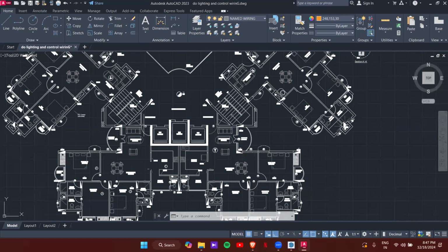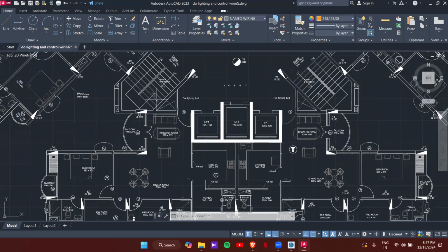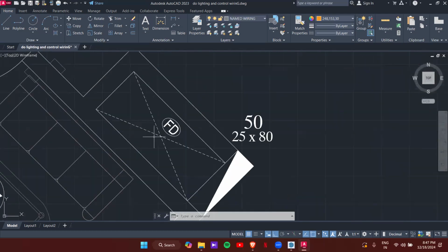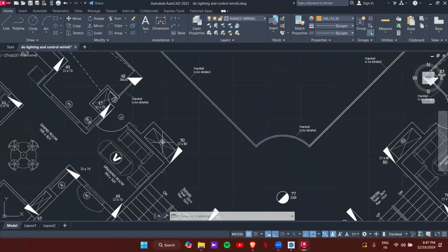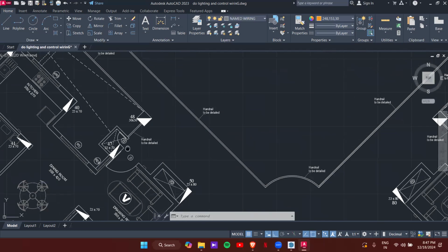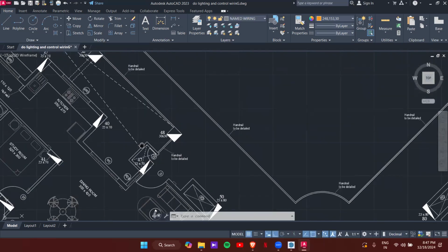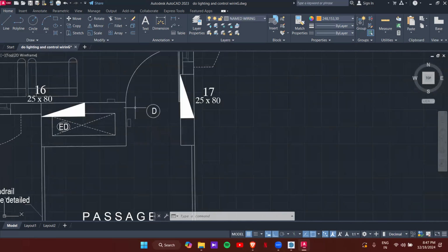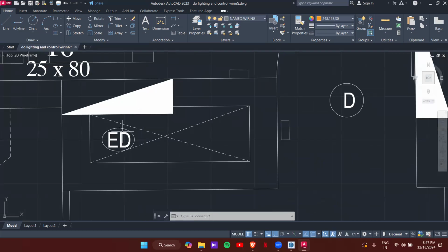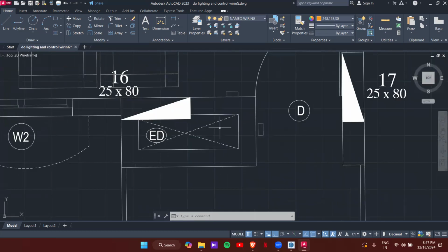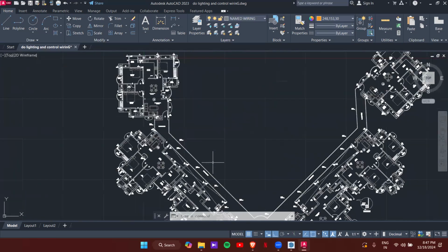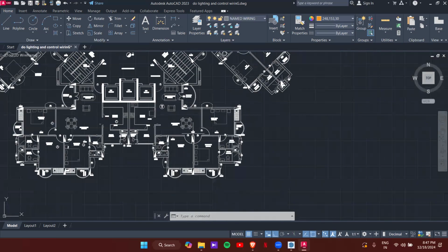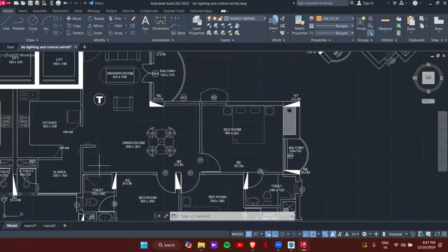Similarly, for the electrical service we'll also have one shaft, I think somewhere around here. Again, FD means fighting shaft. Here you can see, this is ED, meaning electrical duct or electrical shaft. Through here we'll be taking the electrical cable trays and cables, everything will be taken to this particular shaft. So that's it. That's the outline of this drawing. Okay, clear.